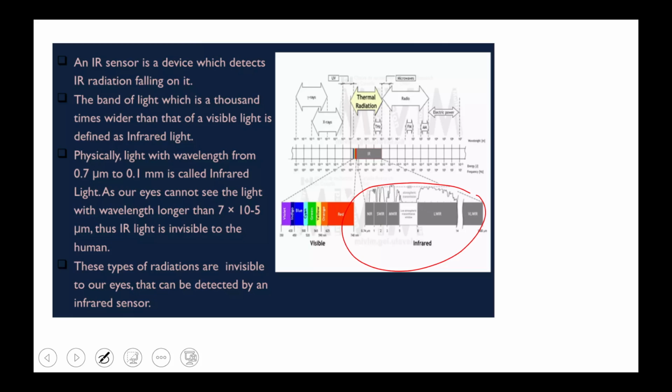The whole source of solar energy has some spectrum of light, and it has particular wavelengths. UV light should be 365 nanometers, deep UV should be 280 nanometers or 100 nanometers. IR should start from 700 nanometers to 1500 nanometers. So 700 should be the near infrared light and 1500 should be far infrared light. You have to distinguish which light you want to use, and according to that you have to fabricate your sensor, choose your materials and device.